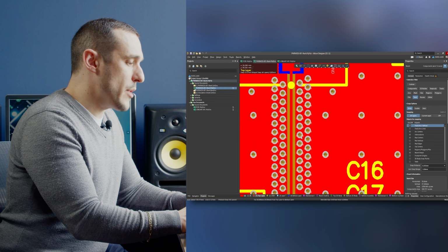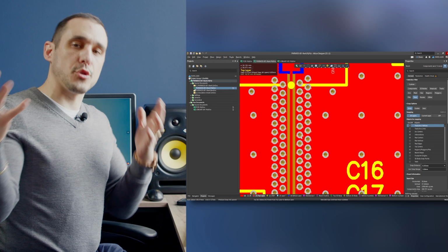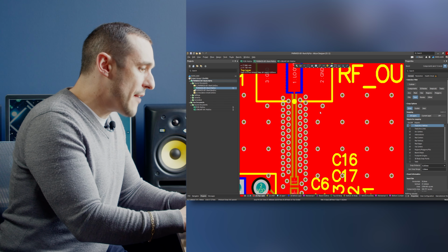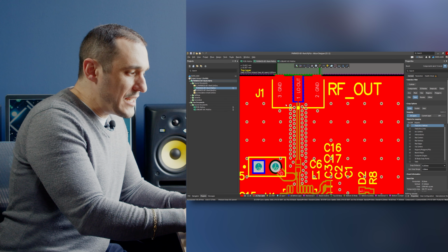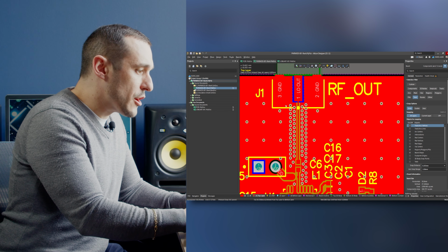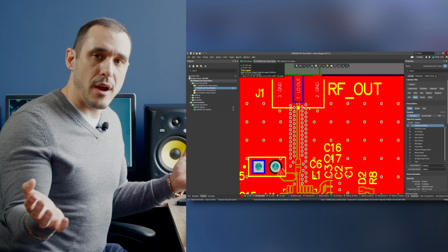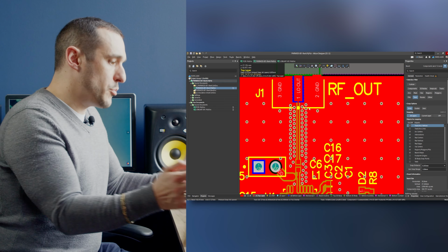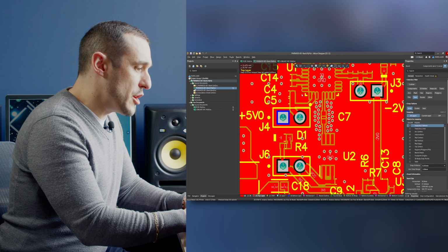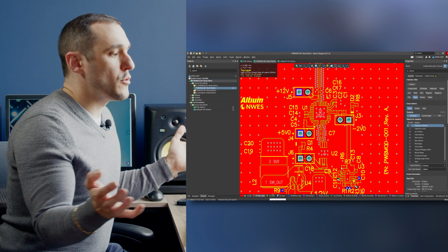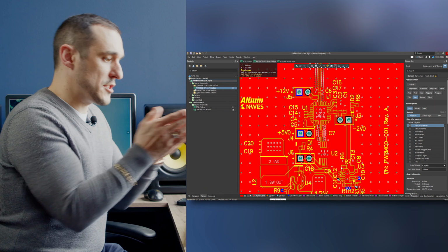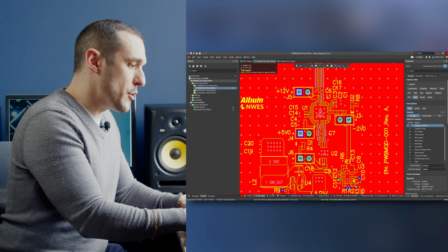So we put this into a coplanar waveguide. And in order to create a coplanar waveguide, we have to have copper pour up on the top layer. At minimum, we would need to have the coplanar ground here in this region for the coplanar waveguide. However, I've decided to put it everywhere because we also have the RF line in other locations on this design. And so that provides a lot of shielding. It allows us to put the via stitching around those lines.